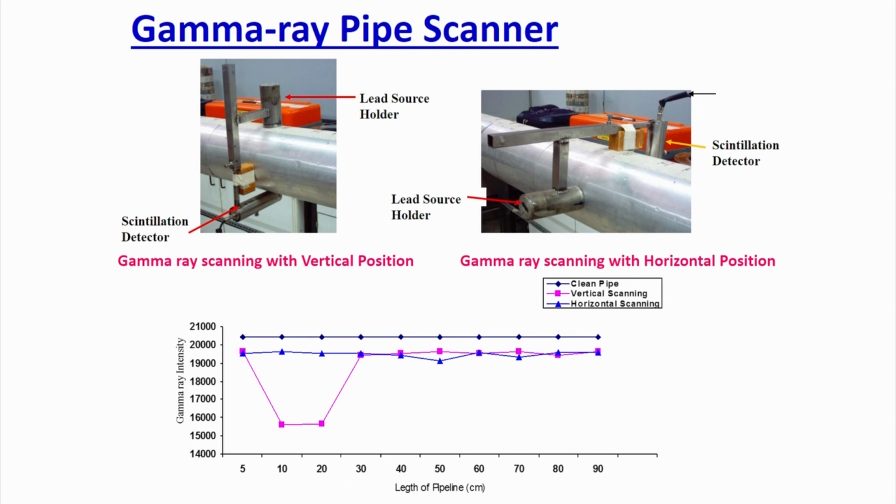Suppose a blockage happens in the pipeline, okay, not a buried pipeline, but on top there is some blockage or something. You can again do the pipe scanning. Wherever there is no blockage, the count will be flat; at the blockage point the attenuation will increase. So, you can find out that okay, this tube has been blocked. You can scan vertically, you can scan horizontally. In corrosion, suppose something internal has fallen down or some blockage has been created, definitely that blockage has a different attenuation. Now, attenuation will increase, so your count will reduce; the intensity you are recording will immediately decrease.